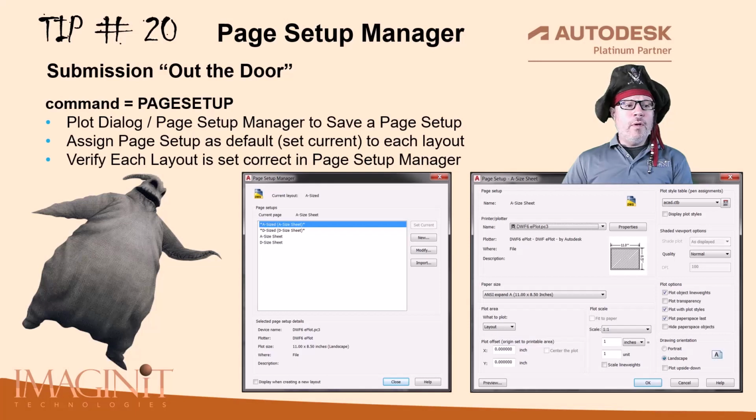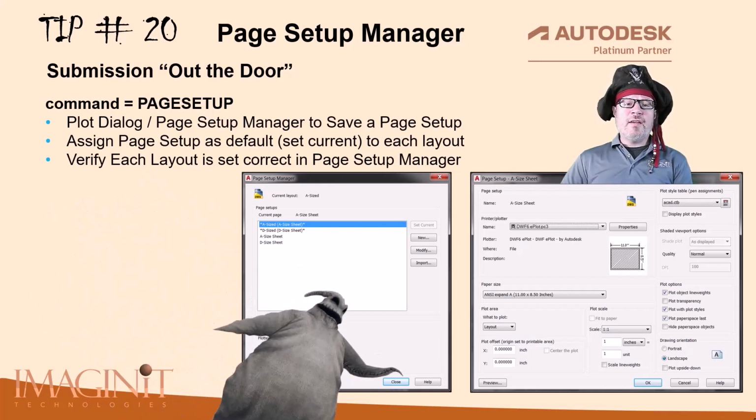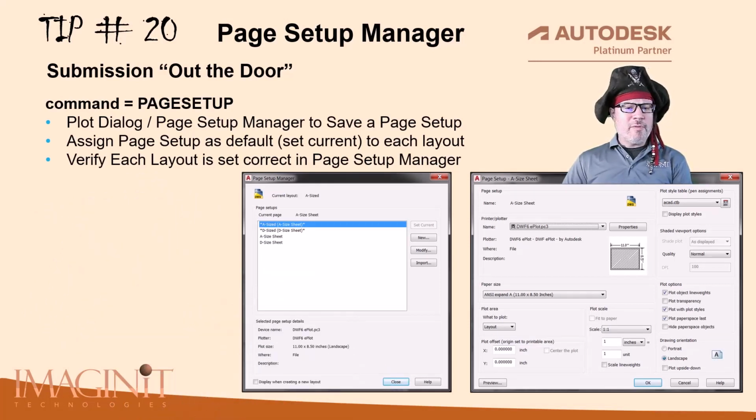With tip number 20, we will start talking about submissions and getting your projects out the door, starting with creating the setup of your prints using the Page Setup Manager. You can set up all of your sheets with correct sizing and plot setups through the Page Setup dialog box.